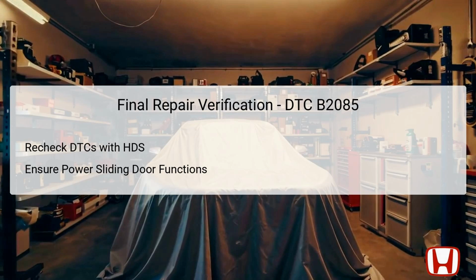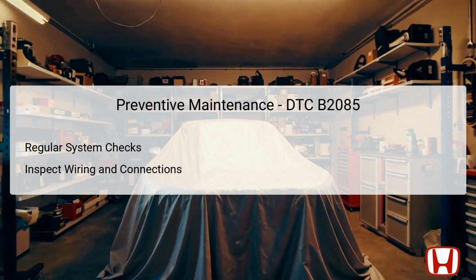Preventive maintenance is essential in maintaining the longevity and reliability of the right power sliding door mechanism. Regular system checks allow technicians to pinpoint potential issues before they escalate into significant failures. It is advisable to inspect the wiring and connections periodically, especially near areas where abrasion may occur due to movement. Ensuring that the half-latch switch functions properly and has no obstructions will aid in preventing future error codes from arising.